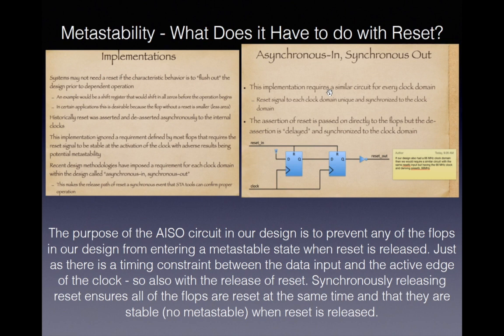To resolve that, the asynchronous in, synchronous out circuit was defined. In this case, when the reset in goes high, the reset out goes high. When the reset in goes low, following the first clock edge, the first flop gets set.